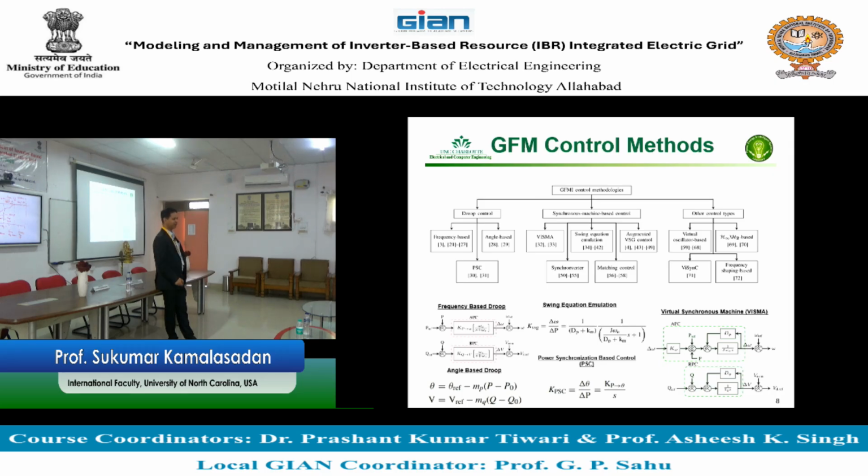For example, for the inverter output you create a sinusoidal oscillator. You put the oscillator without damping, and it follows a periodic waveform like an oscillator. That oscillator frequency I control to 60 Hz. So I have an oscillator output, which is called a virtual oscillator, and then I use control for the virtual oscillator. Forget about all the generators. So there are three different buckets of work done by people. One is droop. Second is the synchronous generator. Third is the virtual oscillator.